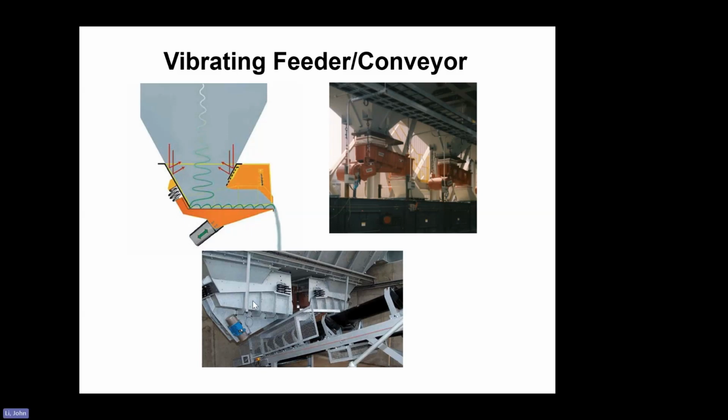George, which part is the drive part? The drive part is here or here, just a vibrating motor. Yeah, very simple. But usually it is controlled by a VFD, so it can adjust the vibrating frequency, so as to adjust the feeding rate.